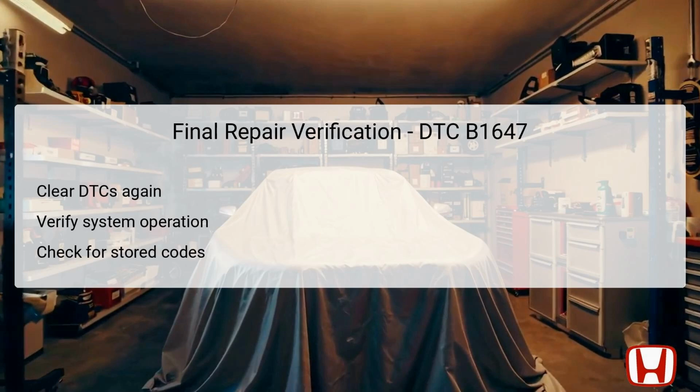The technician should pay close attention to how the system responds to the key fob and whether it consistently unlocks the doors or performs functions correctly. Furthermore, it's essential to check if any DTCs remain stored in the system that could indicate issues have not been fully resolved. This verification phase plays a pivotal role in ensuring that the repair efforts were adequate and that the system is restored to fully operational status.